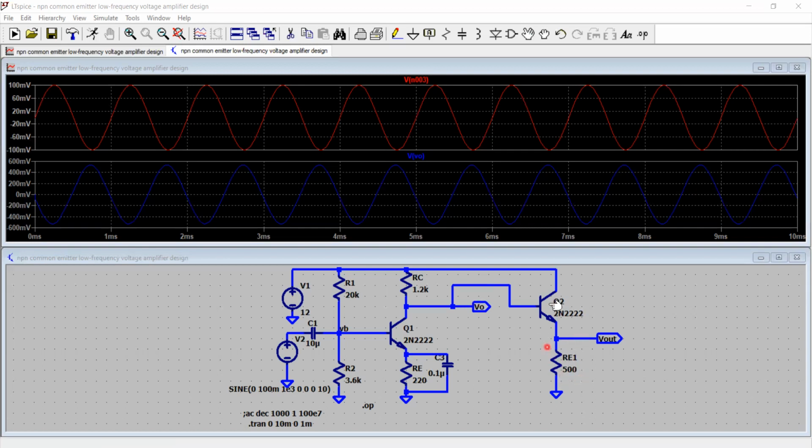Now, having done that, the voltage gain offered by this second stage would be less than 1, or approximately 1, because we've seen that the output will be the voltage at the base minus the forward voltage drop of these transistors. Okay, and now we have plotted VO. Now it's time to plot V out, so we'll do that.